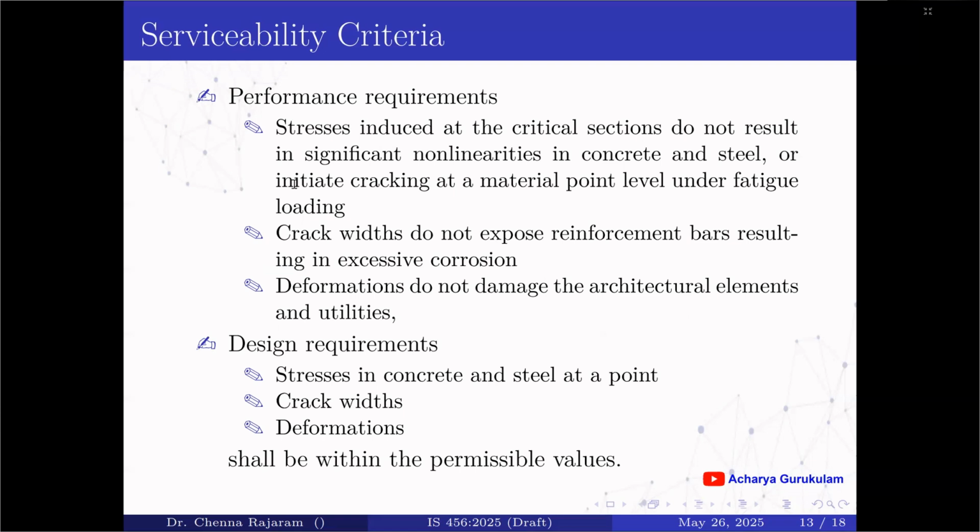Next, serviceability criteria. The performance requirements are that the structure shall possess sufficient stiffness to ensure that stresses induced at the critical sections do not result in significant nonlinearities in concrete and steel or initiate cracking at the material point level under fatigue loading. Crack widths do not expose reinforcement bars resulting in excess corrosion. Deformations do not damage the architectural elements and utilities under the action of loads applied as per the basic wind